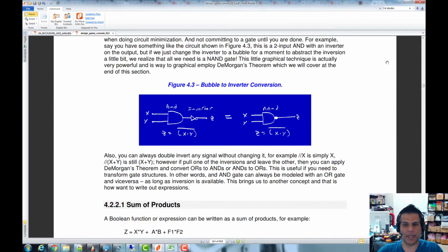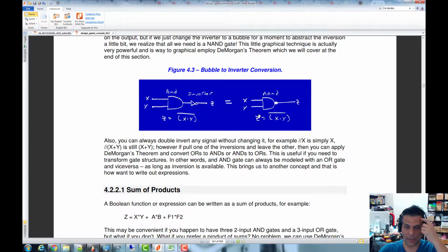All right, so again, I'd like you to read through this, but I'm just going to kind of go through this. So here's another example. So this is saying that z equals x and y, right? And we've just got the bar over there. Just showing graphically the bar is the notation that you would normally use. And there's physically an inverter there. This whole thing creates a NAND gate, right? That's equivalent to this right here. All right, and again, the exact same. Z equals x NAND y, all right? Or you could say z equals x and y inverted if you want, but that is the NAND gate, all right? So if we discretely have an AND and an inverter, that's the same as a NAND gate, all right?